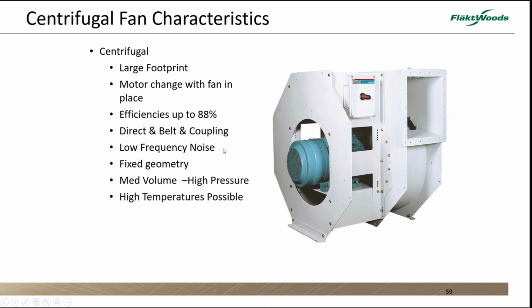If you stand a centrifugal fan beside an axial flow fan for the same duty, you will say, "Ooh, the axial flow fan is much more noisy." But the characteristic of the centrifugal fan is low frequency noise. And low frequency noise is difficult and expensive to get rid of.